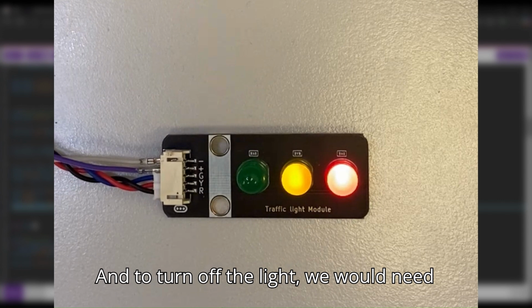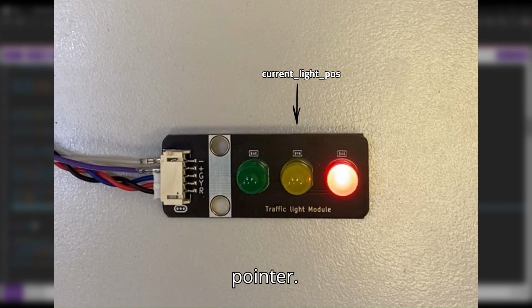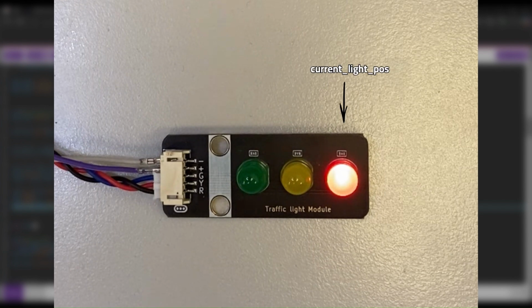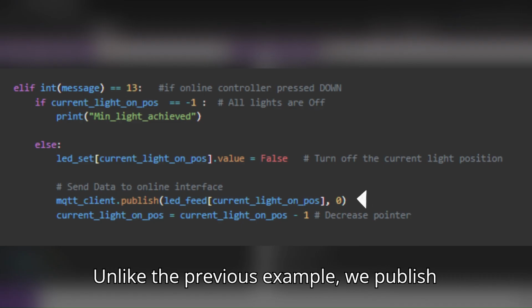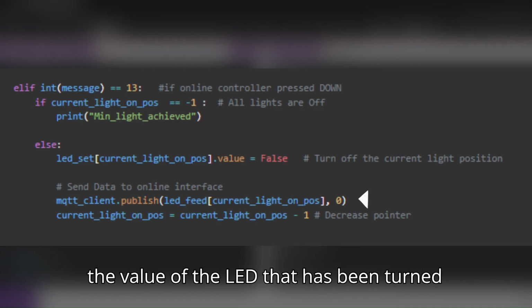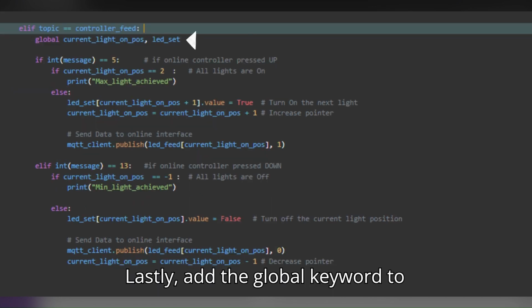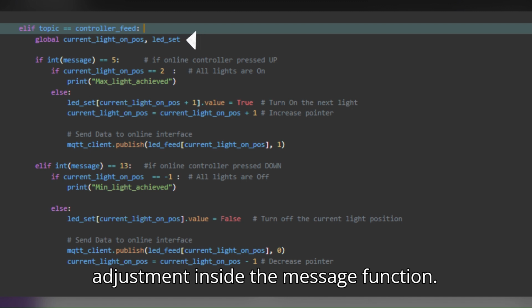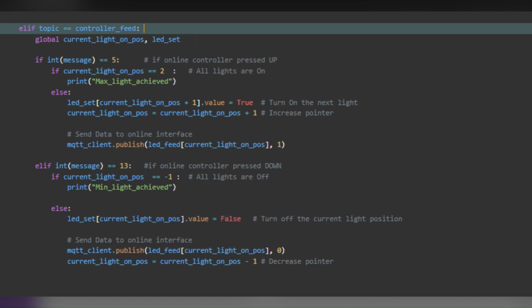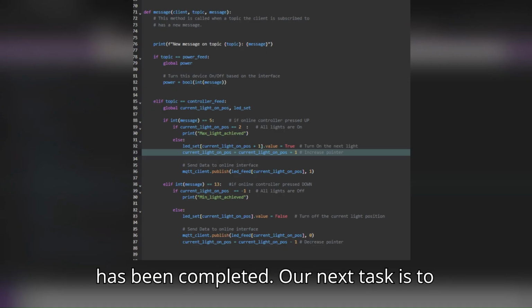And to turn off the light, we would need to turn off the LED on the current pointer first, and then decrease the pointer. Unlike the previous example, we publish the value of the LED that has been turned off before the pointer changes. Lastly, add the global keyword to LED set and the pointer for any adjustment inside the message function. The message function of the MQTT client has been completed.